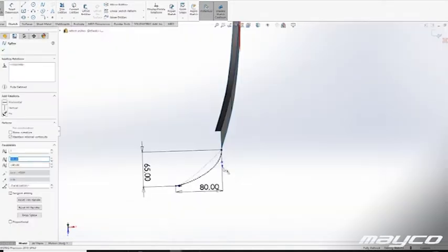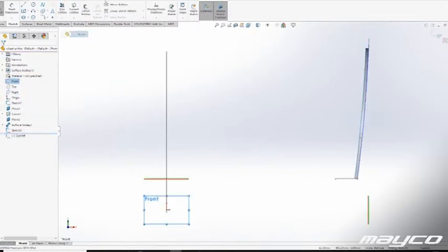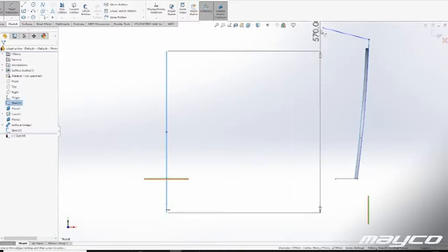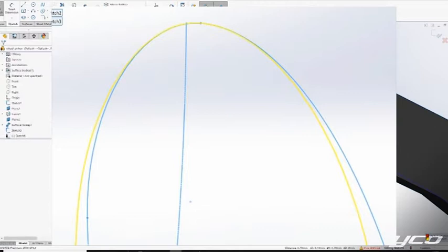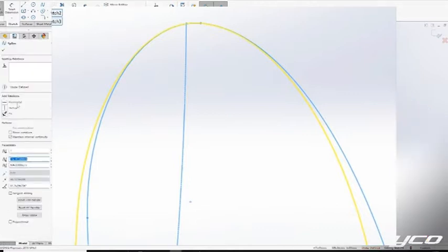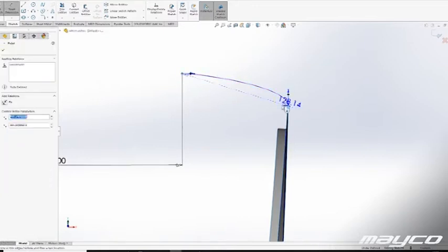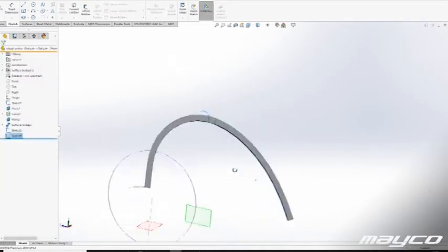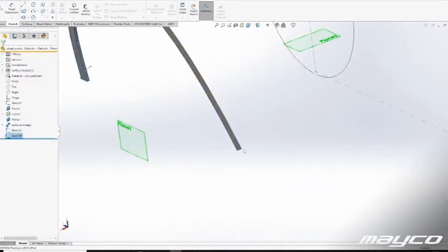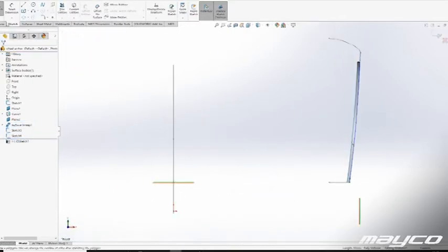So I have a flat sketch on a surface, and I have a sketch on another surface that tells the first sketch how I want to have it in 3D space. The flat sketch will actually become a curved three-dimensional sketch, and that one will give me the curvature of the wheel arch, so that the bottom of the tire will stick out of the wheel arch, but the top of the tire will actually fall inside of that wheel arch.